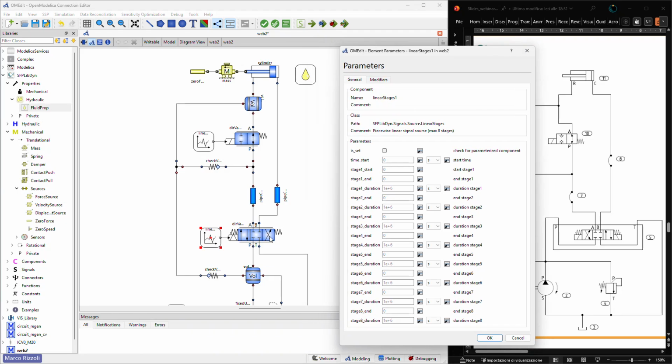I need to activate the right side of the distributor, so the solenoid needs to act in pulling. So I will stay at 0 for 1 second, and then I move to -1, that is a pull signal in 0.1 second, and remain at -1 for 2.9 seconds.